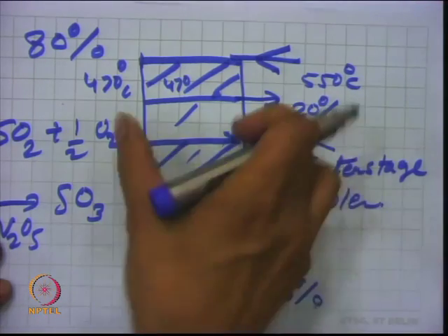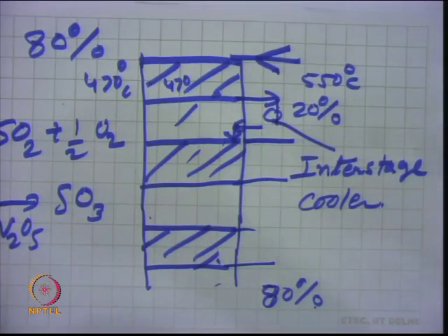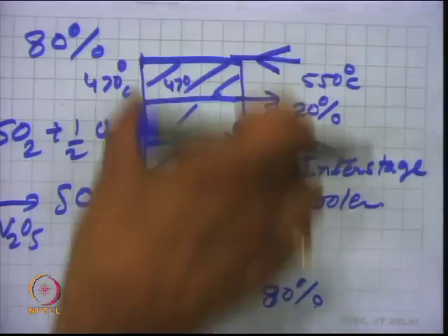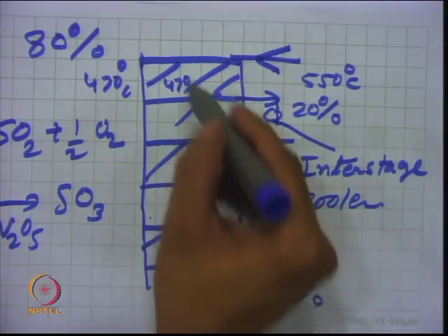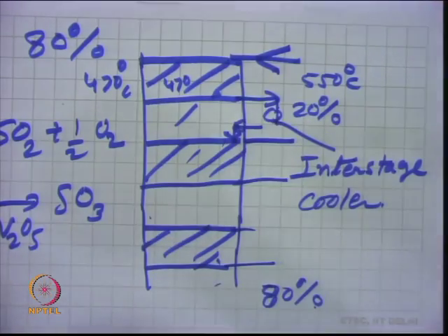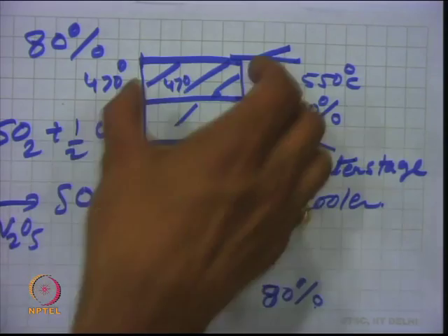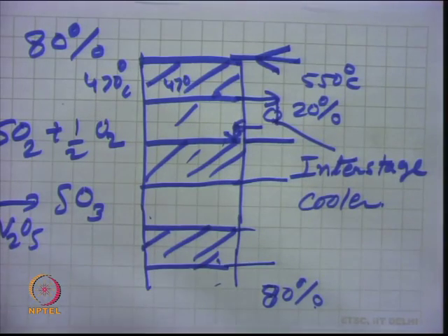In the case of a fixed bed reactor, heat removal may be an issue. When the reaction is highly exothermic, one cannot use a single bed of catalyst in the reactor. The second option is that we can have multiple tubes, because once you have a large number of tubes in this kind of cylinder, the surface area per unit volume of those tubes will be very high, because it is a small diameter tube.